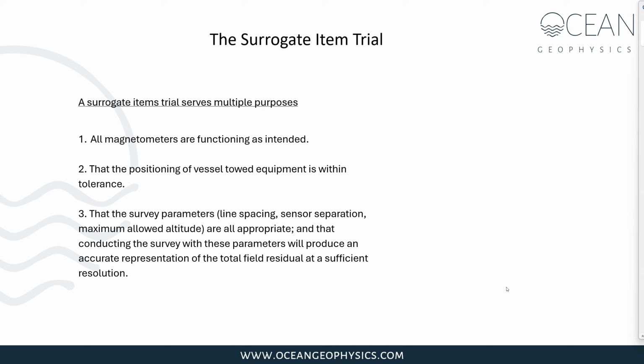It proves to the client that all the magnetometers are functioning as intended, that the positioning of the vessel's towed equipment is within tolerance, and that the survey parameters, the line spacing, the sensor separation, the maximum allowed altitude are all appropriate, and that conducting the survey with these parameters will produce an accurate representation of the total field residual at a sufficient resolution.